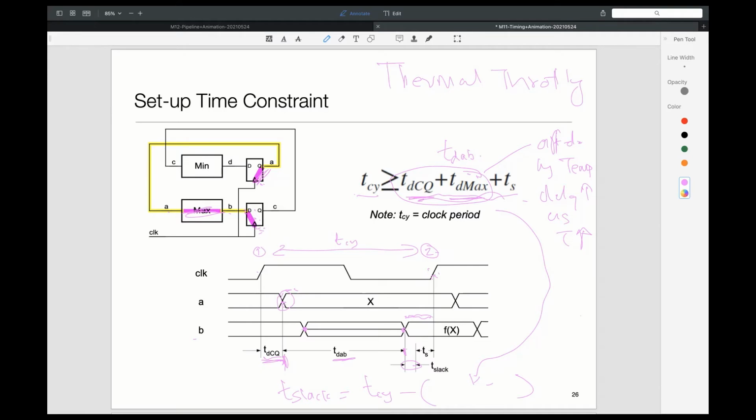Okay, so there's a lot that goes on in this clock rate management. But underlying it is this equation and the thermal part. The two go hand in hand. Very roughly speaking, the higher the clock rate, the more activity you are doing per unit time, and therefore you'll be moving more energy per unit time. In other words, you'll have more power consumption.